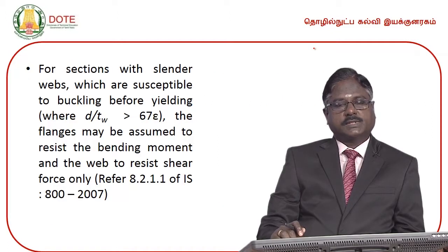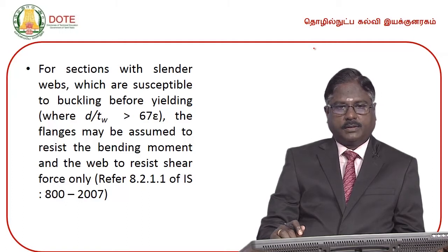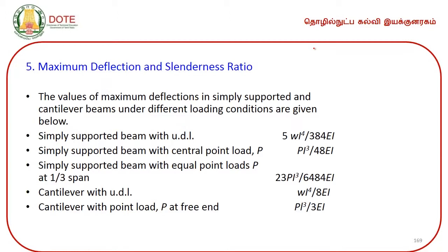And for sections with slender webs which are susceptible to buckling before yielding, the flanges may be assumed to resist the bending moment and the web to resist shear force only. Maximum deflections permitted for the simple beams.